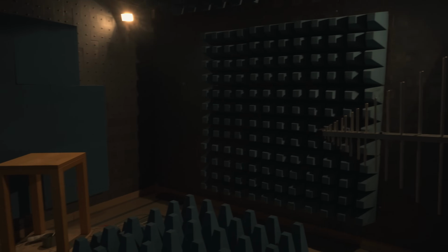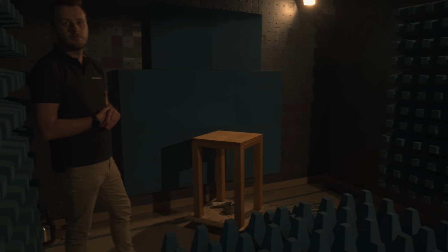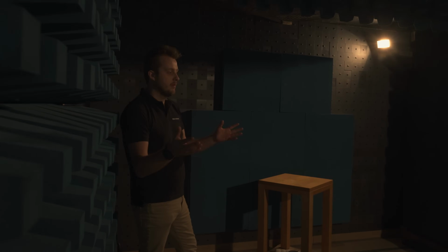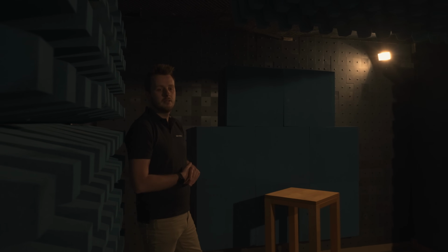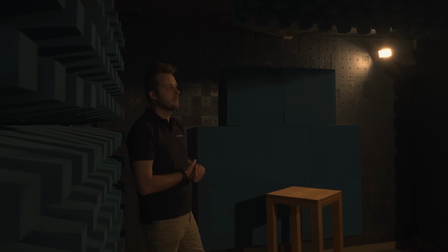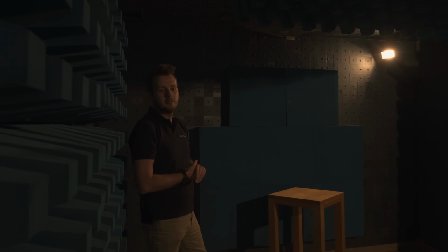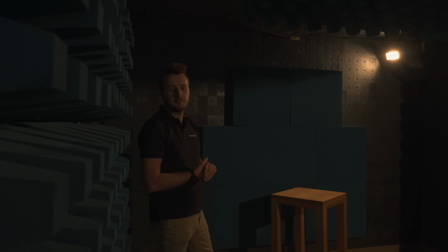It's an automotive size gauge, so it's not a fully compliant 3 meters, but it's around 2 meters 50, and from there we can give them, or customers, an idea how big their emissions are versus the limit. So all the red flags about emissions, I would say for 90% we can see.